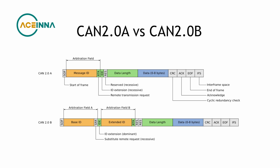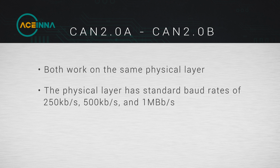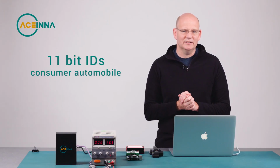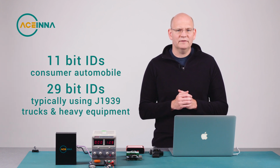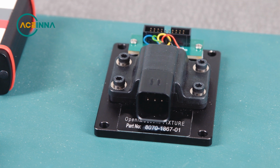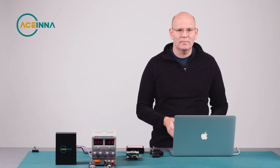Now, the CAN bus specification itself has 2 message standards for messages: CAN 2.0A with an 11-bit identifier and CAN 2.0B with a 29-bit identifier. Both work on the same physical layer. The physical layer has standard baud rates of 250 and 500 kilobits per second as well as 1 megabit per second. In my experience, you commonly see both the 11-bit IDs, for example in consumer automobiles, and you see 29-bit IDs, typically using the J1939 protocol in trucks and heavy equipment. So we will briefly discuss both message types and how to build applications with both message types using Open IMU 300RI.